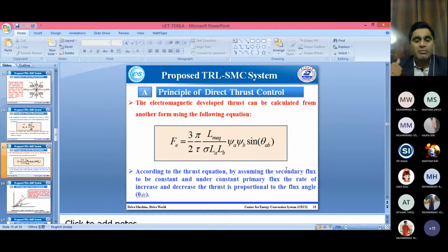Whenever we talk about the rotary induction machine, it would be the torque, like IQ. And for the linear induction machine, it is a thrust. So after the slide mode control or the PI regulator in the speed loop, we directly take it as a thrust.